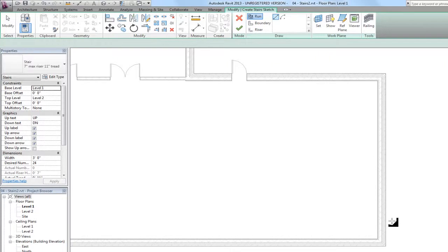building here. So if we move our cursor just near the face of a wall, Revit finds it, and then we click, it actually shifts the stair so that one edge aligns with that wall that you selected. If you look closely near the first point we picked, you can see that there is a 12 risers created and 12 remaining light gray text. If we were to click right now, there would be 12 risers created and 12 remaining.